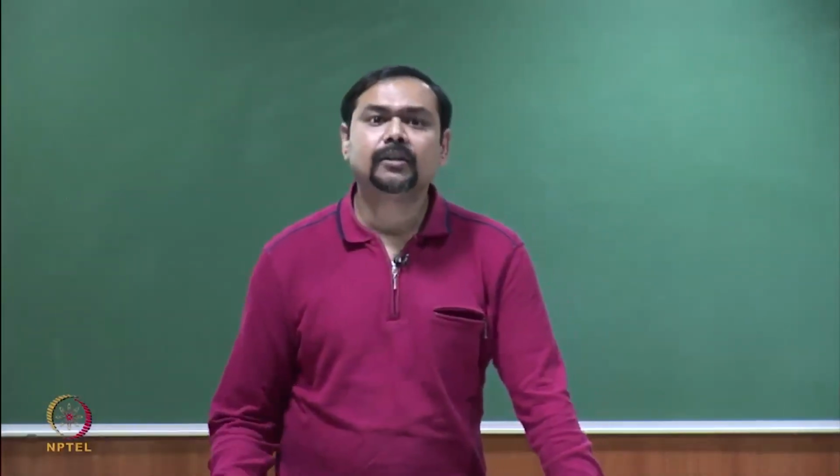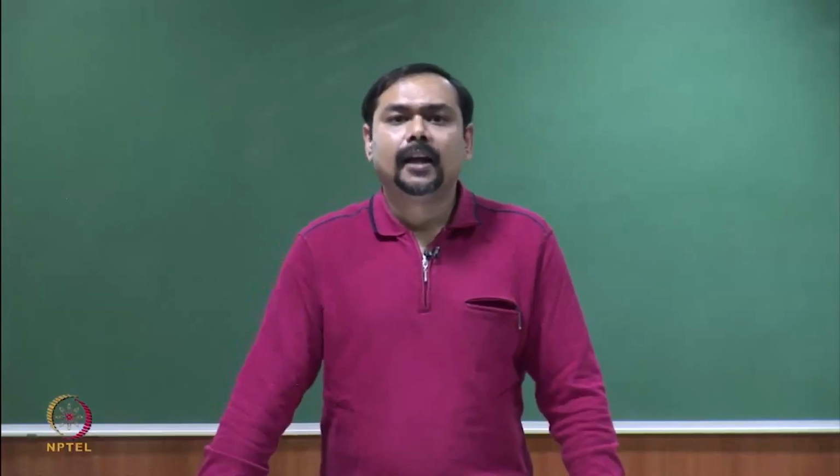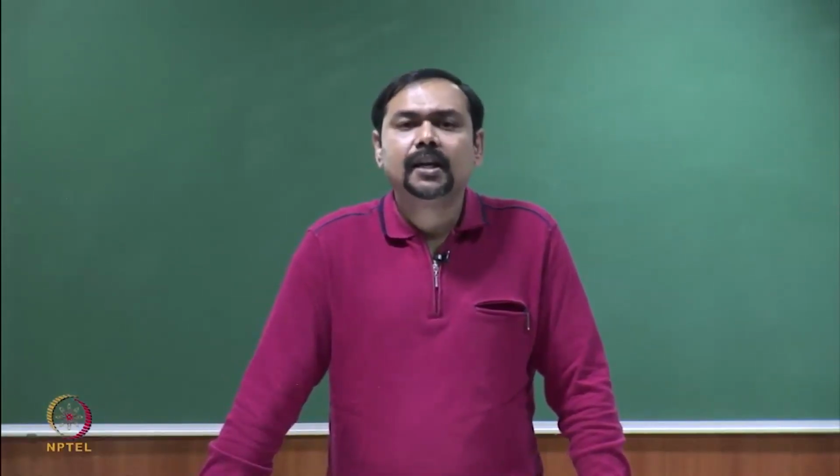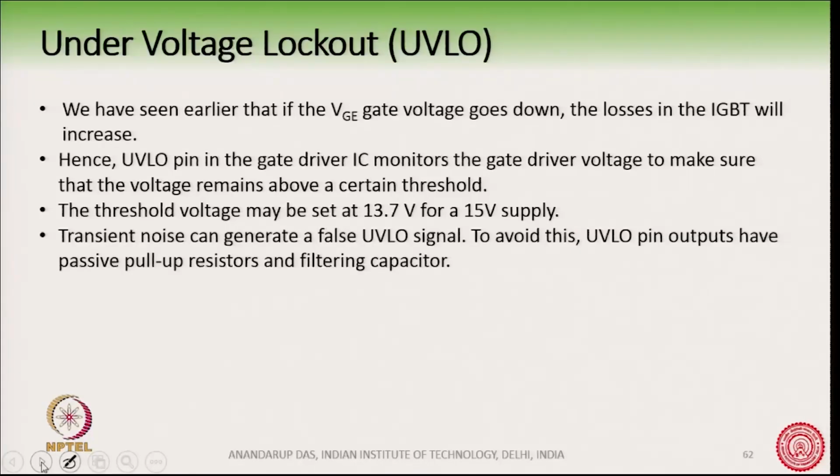There is also something which you will see sometimes being used, the UVLO, under voltage lockout. What is that? Under voltage lockout is also a protective feature in the gate driver ICs. If VG voltage goes very low, then we know that there are associated problems.